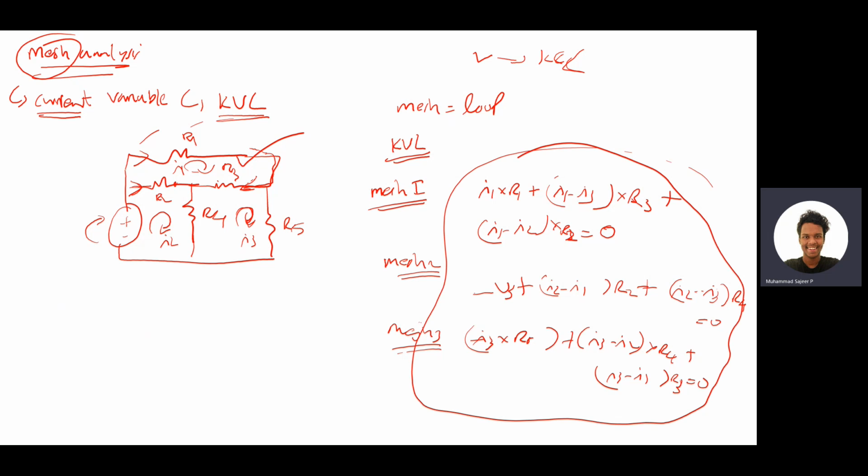From that you can calculate whatever you want. So that is mesh analysis. Now it is all algebra, I mean mathematics: just rearrange, substitute, and that kind of stuff, right? The thing about nodal and mesh analysis is that we call them brute force methods. They just apply KVL and KCL by considering the current and voltage as parameters, but they don't give any kind of insight.